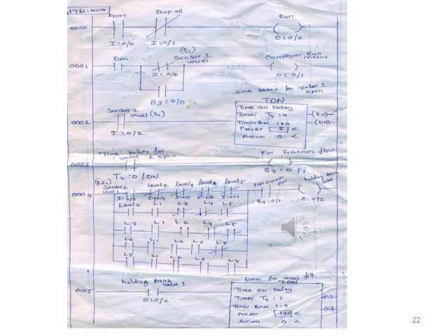When the vessel sensor is sensed, the delay timer TON gets on, with a preset value of 5 seconds. After the accumulation of the preset time, the done DN signal gets on. D for DN. Then binary output B3 gets on. When timer binary B3 is on, then as per requirement of level sensor, level 1, 2, 3, 4, 5, the holding tank valve turns on.